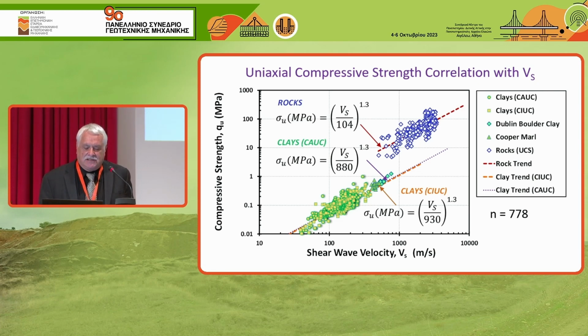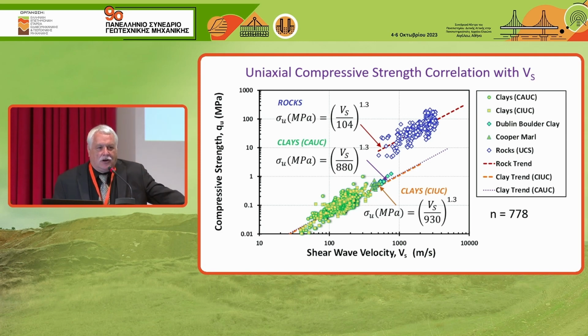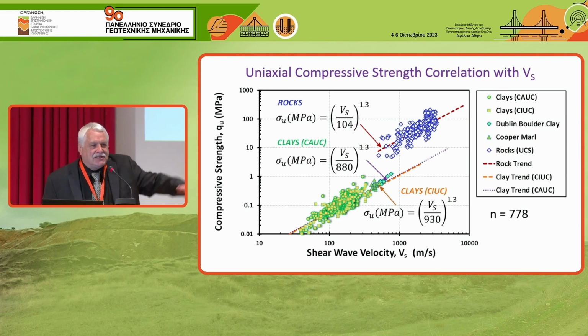So you can see there's a discontinuity as you get up in the clays, as you transition from soft clay to firm clay, stiff clay to hard clay to now fissured clays are going to jump up, as would rocks, because they've mostly got discontinuities, cracks and fissures. So there's a step up there. They shouldn't be tied together directly. But you see the transitions.